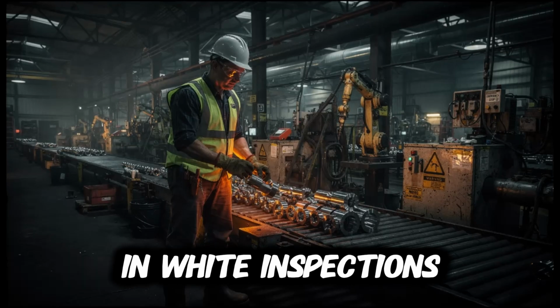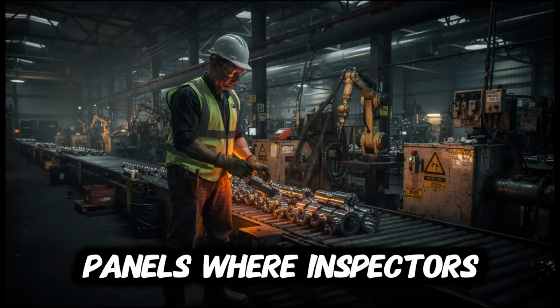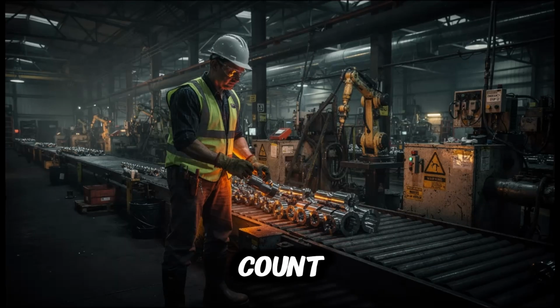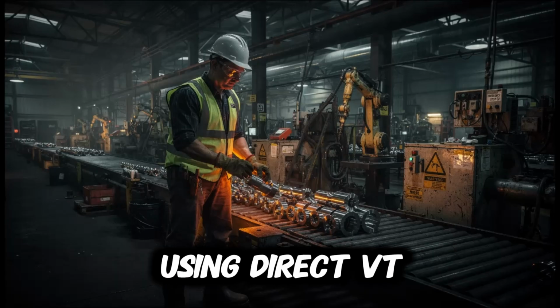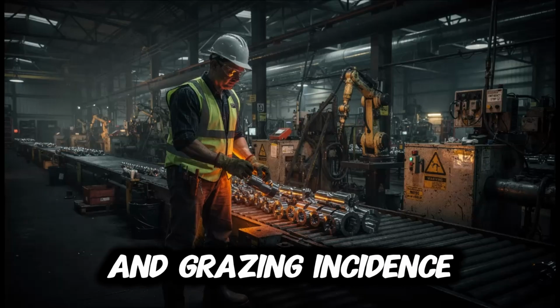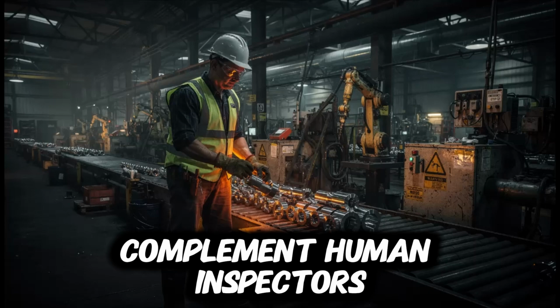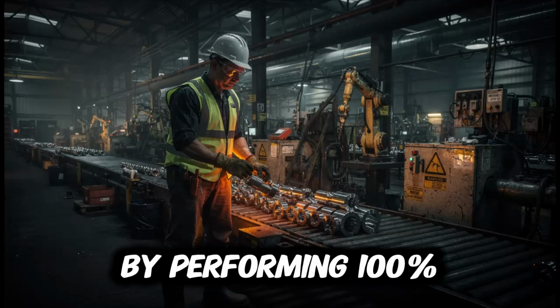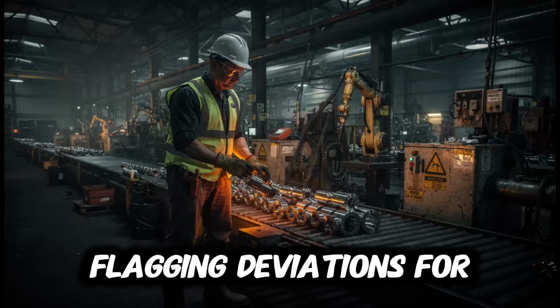Body-in-white inspections focus on weld quality in stamped steel panels, where inspectors verify spot weld count, nugget formation, and absence of surface cracks using direct VT with calibrated magnifiers and grazing incidence lighting. Robotic vision systems complement human inspectors by performing 100% screening of weld seams at line speed, flagging deviations for manual review.